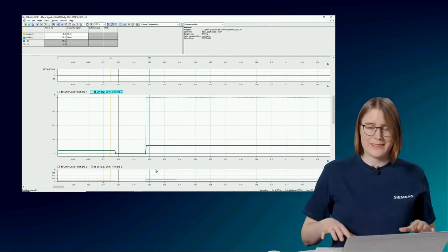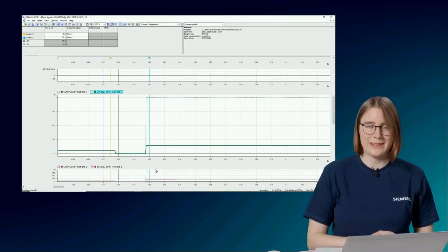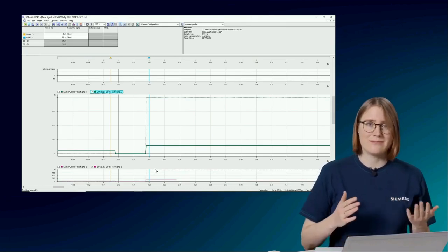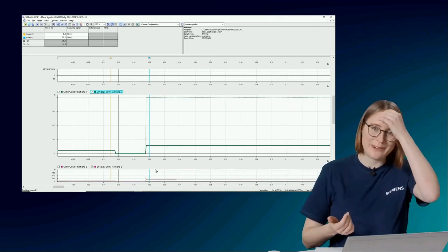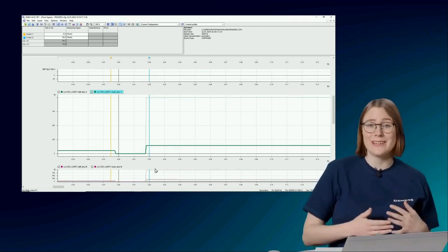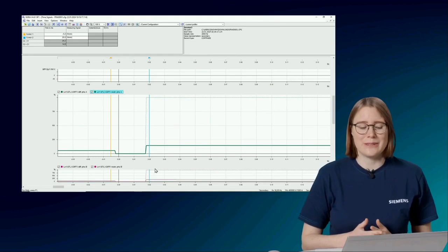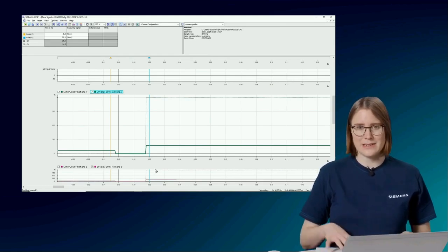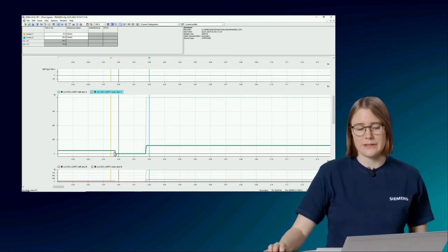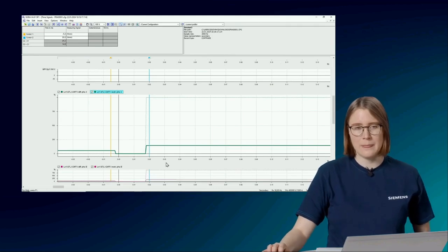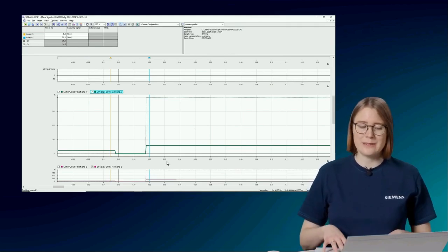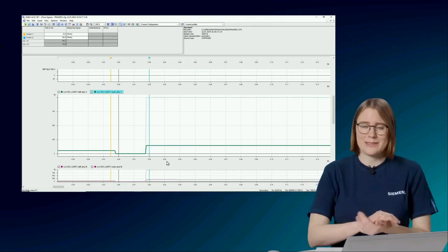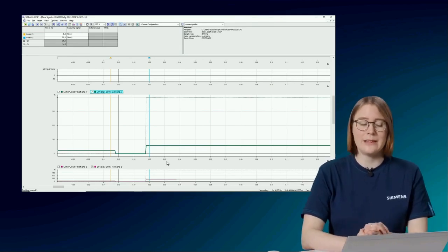But for the sensitive stage, we want to make sure, okay, even if the fault is somewhere at the border, if it is a fault or not. We want to make sure that we have a clear measurement. Therefore, we block the sensitive stage for one time period here, for 20 milliseconds. If you want to learn more about the theory, the algorithms behind line differential protection, we will also have a session about it.